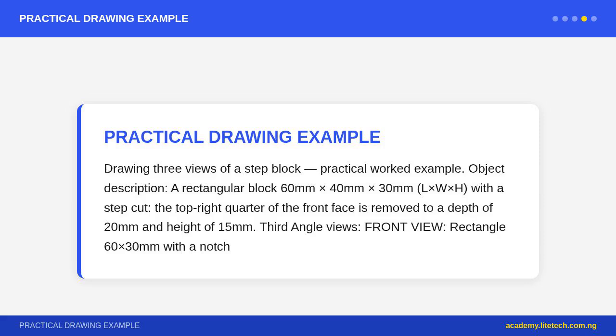Question 2. Where is the plan view placed in third angle projection? Answer. In third angle projection, the plan view, top view, is placed above the front view. This is because the observer looks down from above, and the projection plane, between the observer and the object, receives this view at the top position.